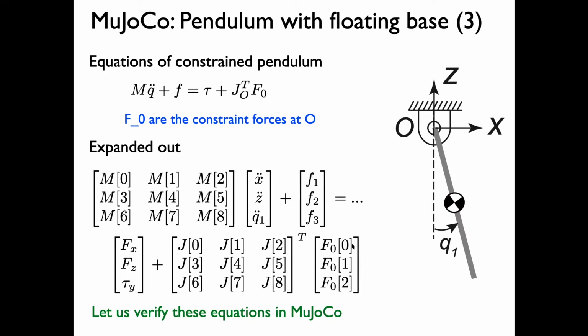Okay, so what I'm going to do is show you that you can actually check these equations in MuJoCo. I did this exercise for a pendulum where I showed how you can verify the equations of motion. I'm going to do the same thing for this system, where I'm going to pluck out M, pluck out Q acceleration, these forces, everything on the right-hand side, and then just equate them and show that it's true. Once we know that is true, then we can do more interesting things with those equations and those forces. So let's just proceed and do just that.